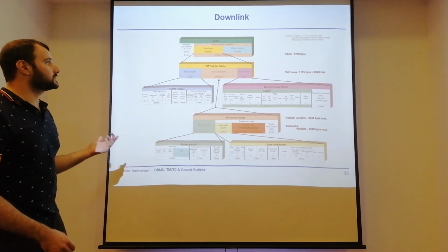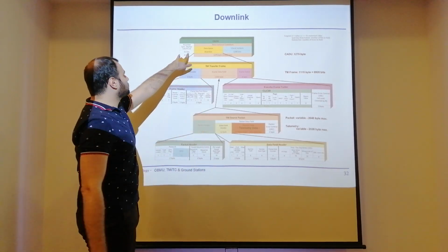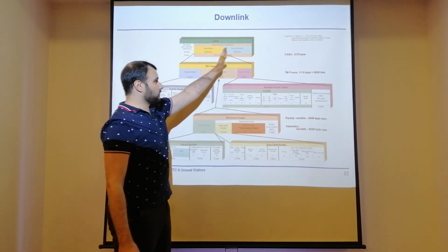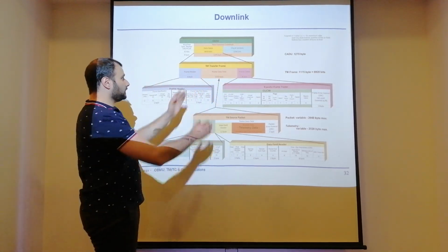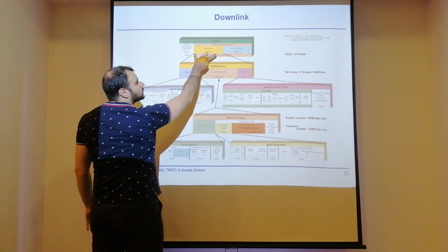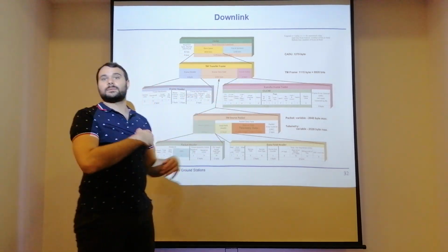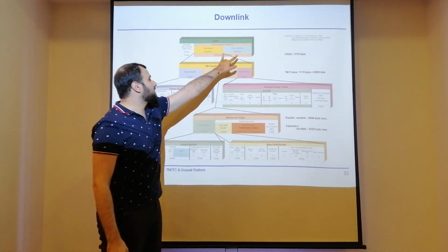And for the downlink, we have the so-called CADUs. One CADU has the synchronization marker and the Reed-Solomon code block. You have your data inside of your Reed-Solomon code block and your Reed-Solomon check symbols at the end to do some error correction. We have some redundancy bits here.